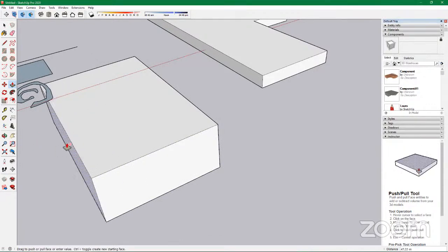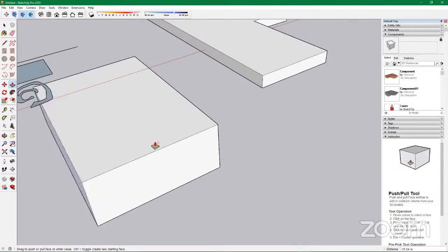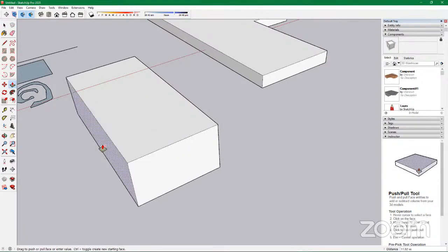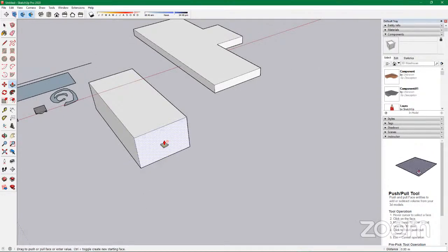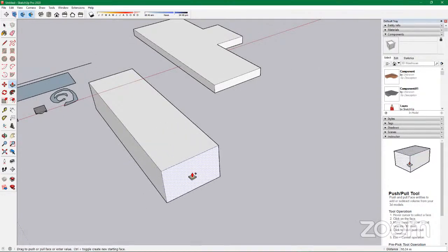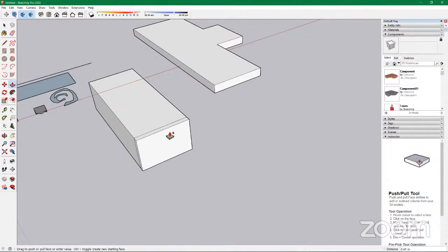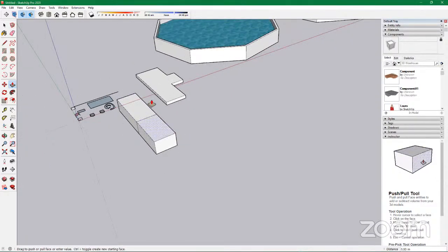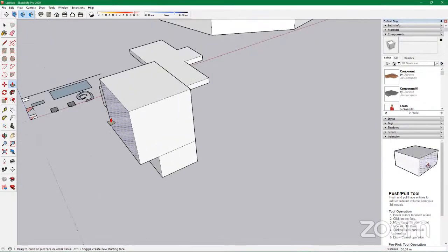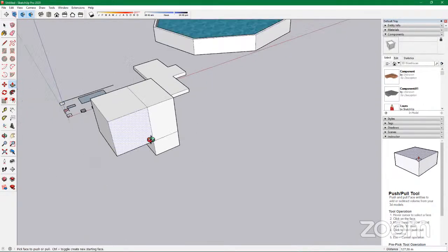Now, if you want to push pull and create something like a marker from where you're pushing from or pulling from, you can click to push pull and then tap the Control key. So it creates that marker showing this was where the object was pulled from or pushed from. So there you have it. Now we can continue and pull upwards and then tap Control. It gives you a demarcation like so. You can do this, tap Control, and it gives you another demarcation like so. Do you understand this?